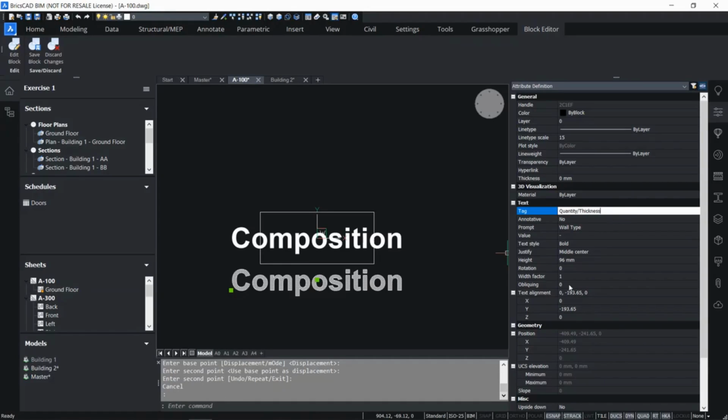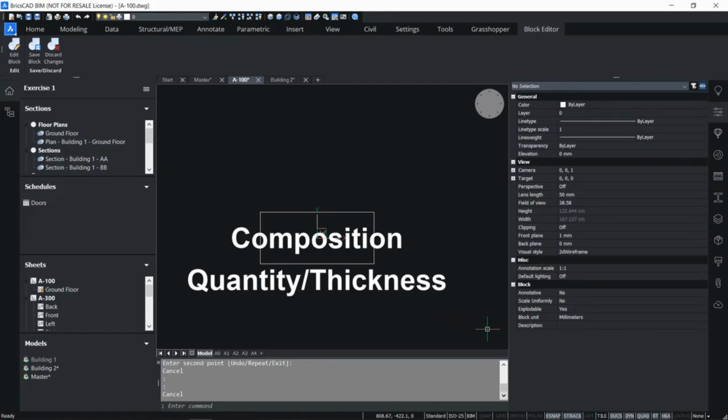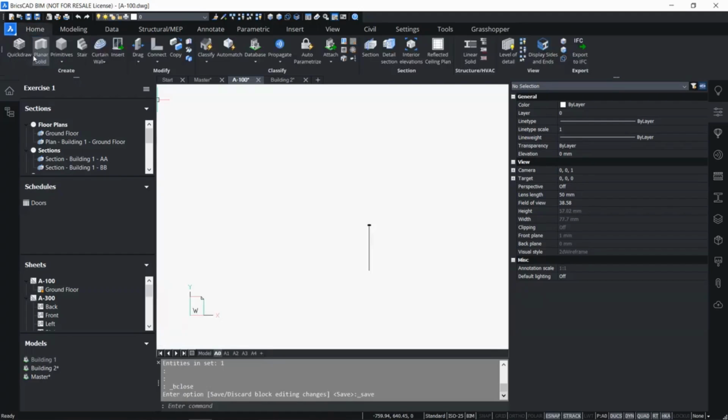And then if you want to have, for example, text alignment X, like this sub value, you should type in text alignment semicolon, and then X, for example. So the syntax you can view in your handouts with a bit more explanation, but in general you have the property category and then the property name itself. If no category is specified, the BIM category is assumed. And you can now delete the rectangle as well and save the block here.